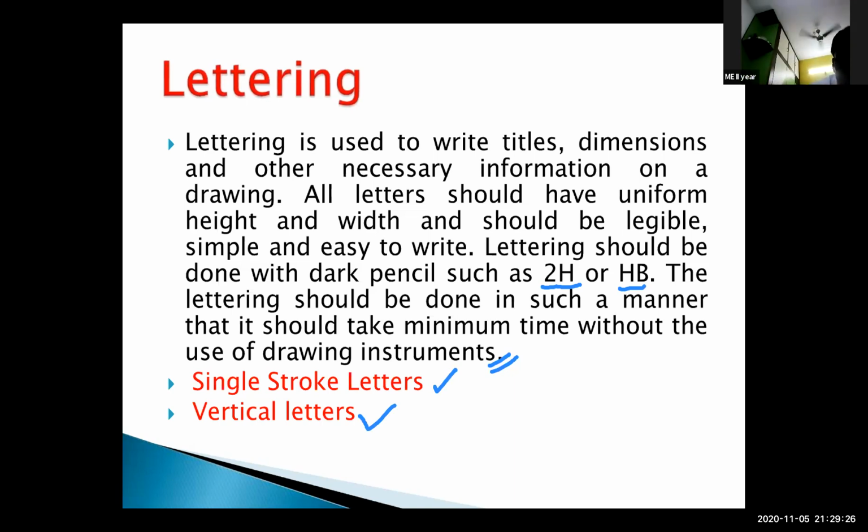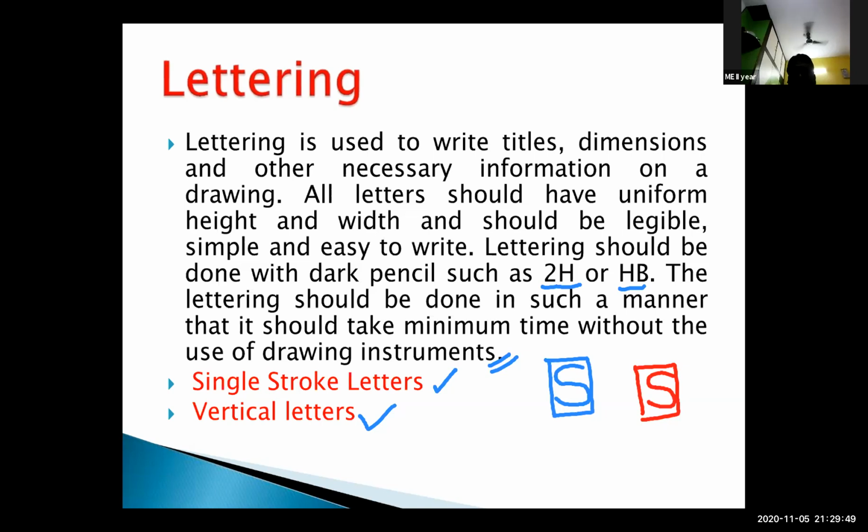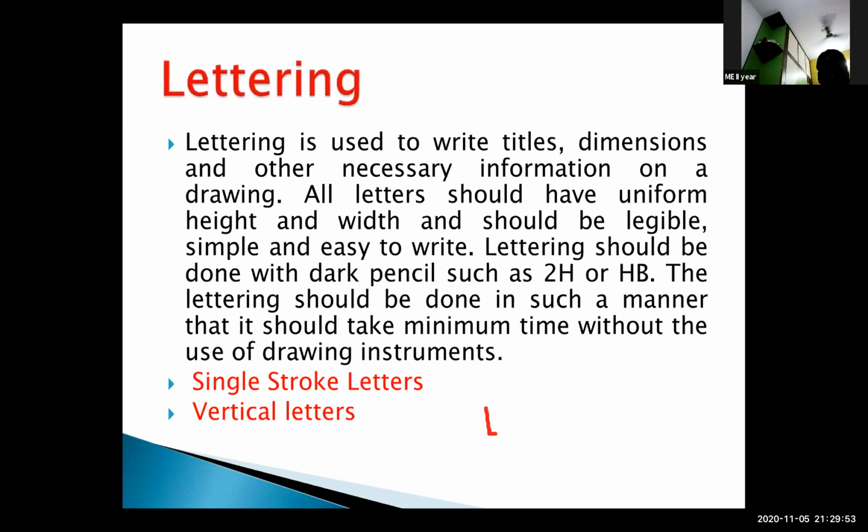What is the meaning of single stroke? The letter has to come with one stroke. In engineering drawing, we have to follow single stroke lettering, and it should be vertical. Like that the lettering should be. We have to write like this.